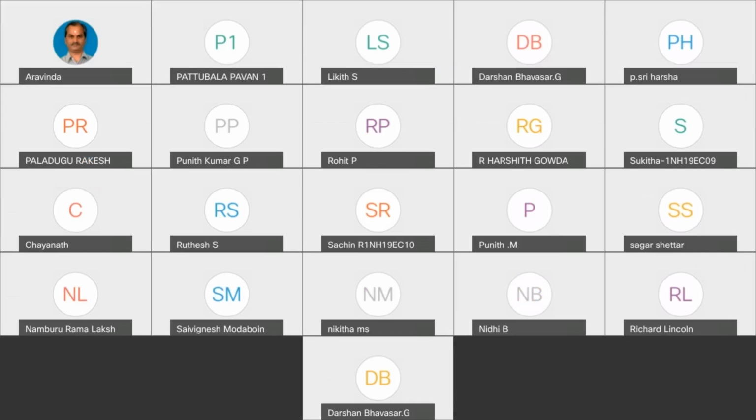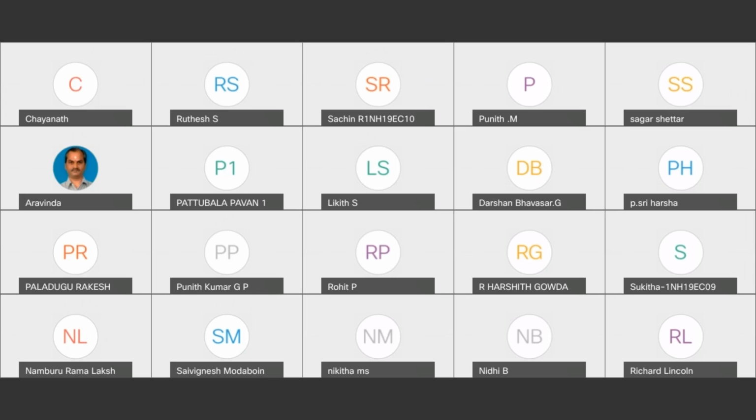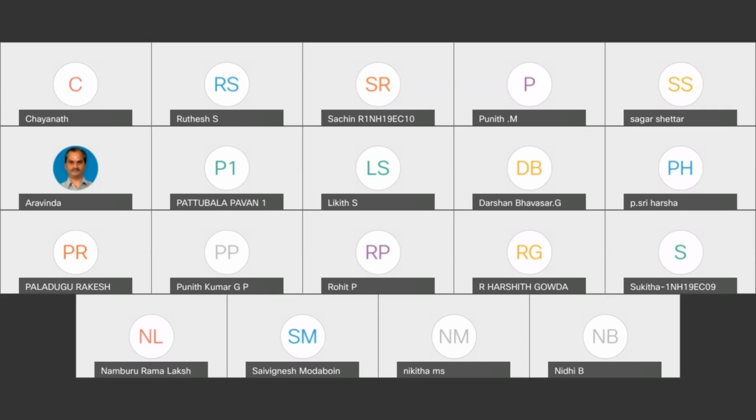Here in FPGA design, we are not worried about making the layout. We are only worried about writing the code and then implementing it using FPGA. But in ASIC Design, not just writing the code. Later on, you'll have to make a physical design also, or you have to make a layout for the circuit which you are trying out, especially in analog designs.